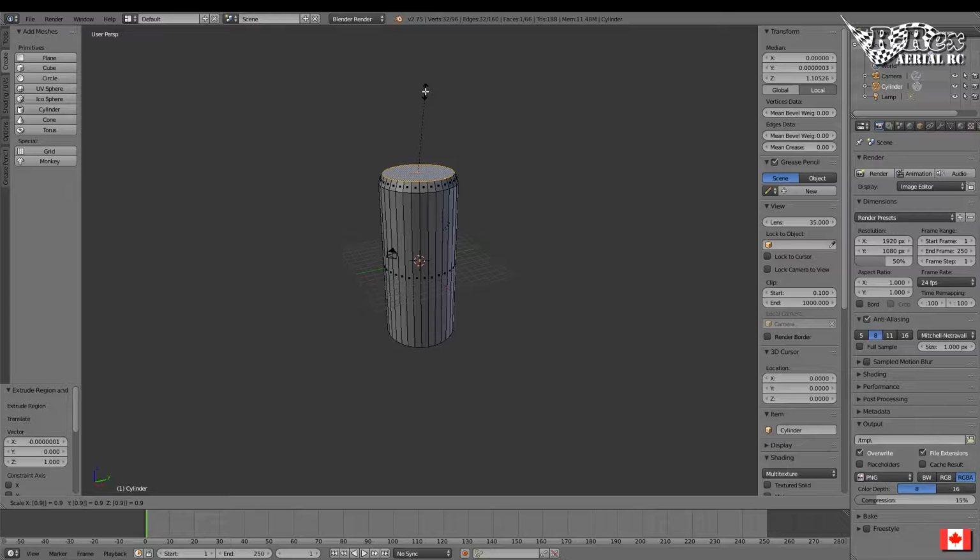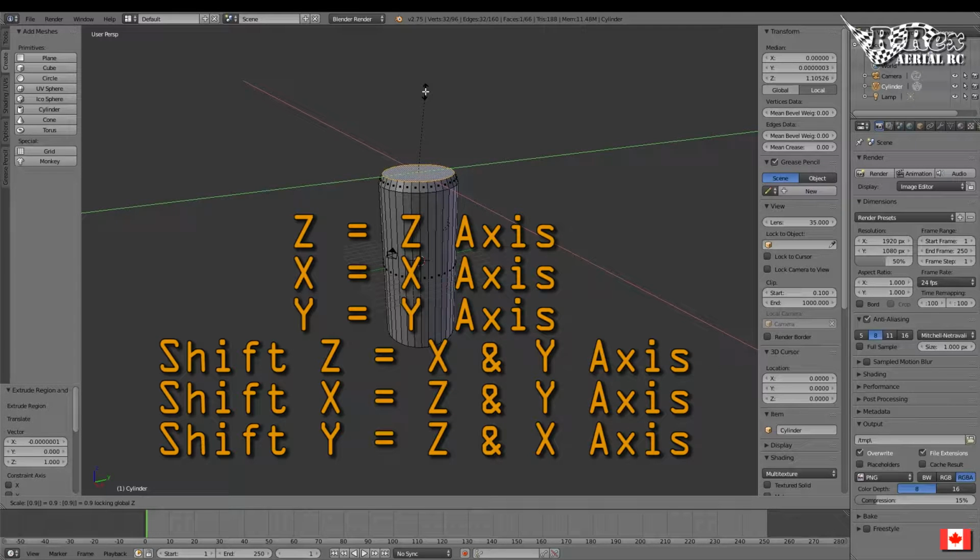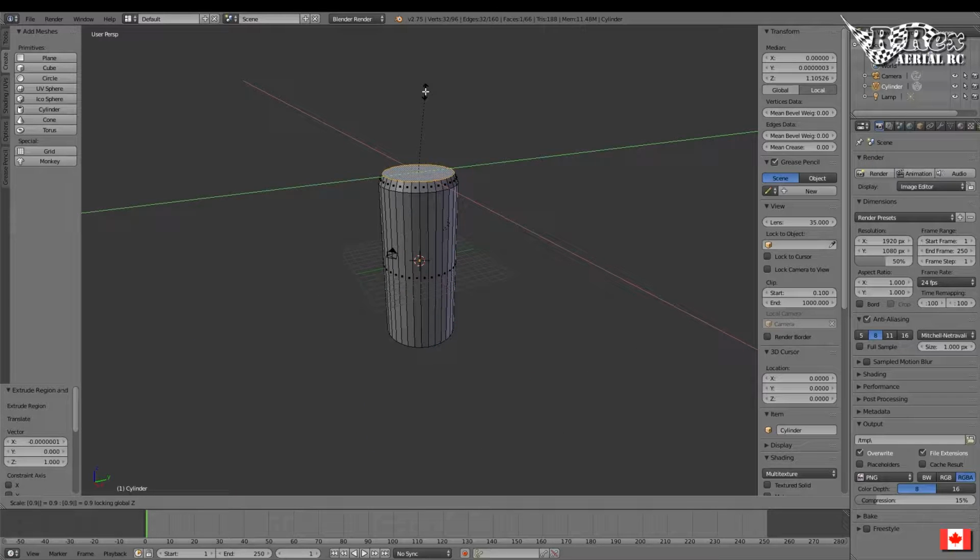The other way, though, let's say you selected a 3-dimensional surface, so you're selecting basically a whole object, and you want to shrink and expand it, what you would do is you would actually press Shift Z, and what that'll do is that'll remove Z from the equation, and now it's going to scale on X and Y. If I was to just press Z on its own, it scales on Z. If I press X, it scales on X. If I press Y, it scales on Y. So what we want to do, though, is we want to scale on X and Y, so you press Shift Z, which just negatives Z out of the equation, and you end up with this.